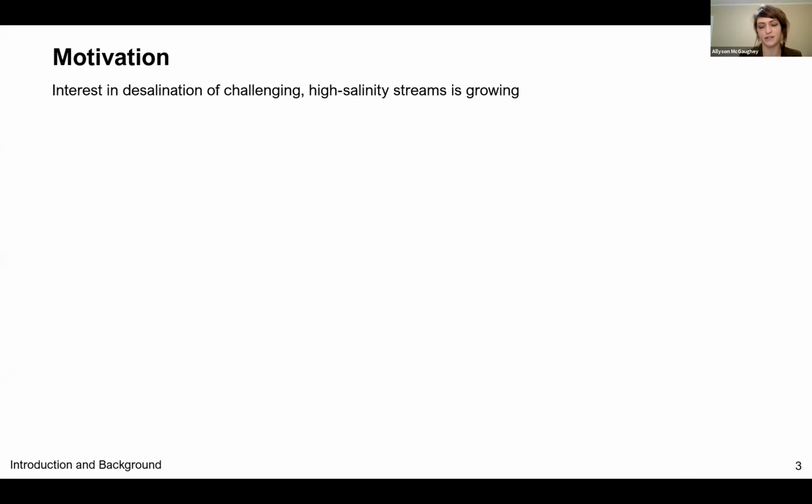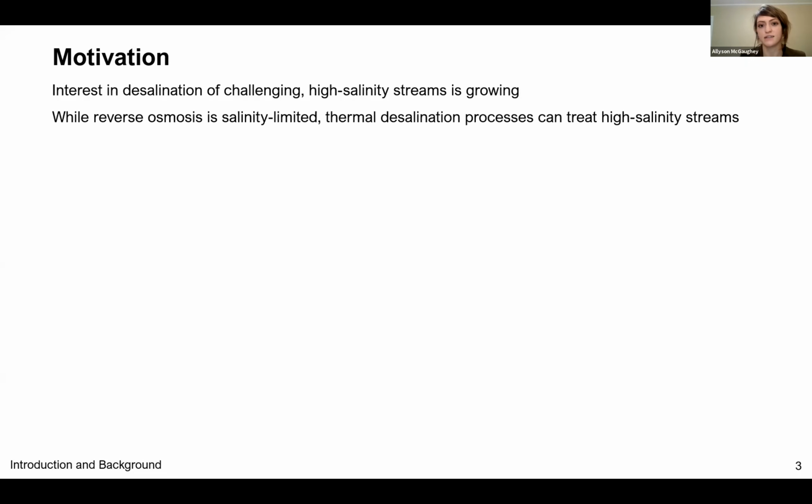As I'm sure everyone here is very familiar, interest in the desalination and reclamation of increasingly challenging higher and higher salinity streams is growing. We would, of course, generally prefer to use reverse osmosis for these applications because reverse osmosis is the most energy efficient desalination technology. Reverse osmosis is salinity limited, at least currently. And thermal desalination processes, in contrast, are able to treat high salinity streams.